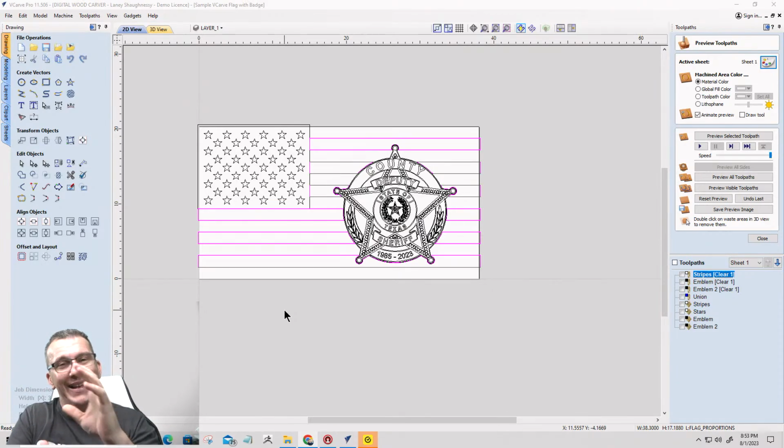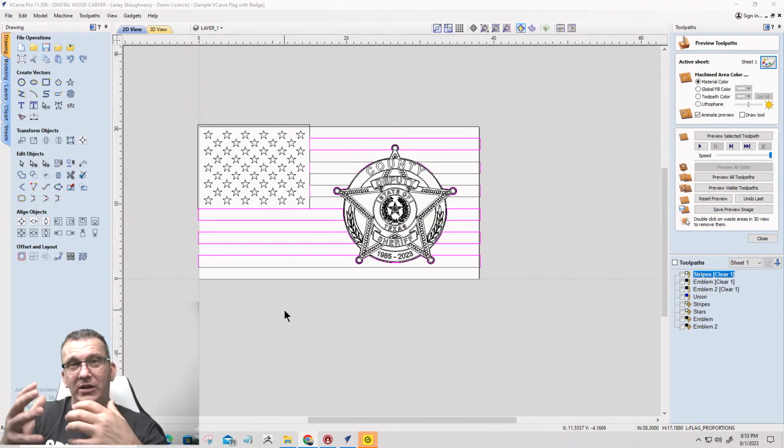That's the other side of the spectrum. You're going too fast on your feed rate, and your bit is spinning too slow. Slow down the feed rate, increase the speed, the RPMs, until you get that good combination where you get a good, nice, clean-sounding cut.